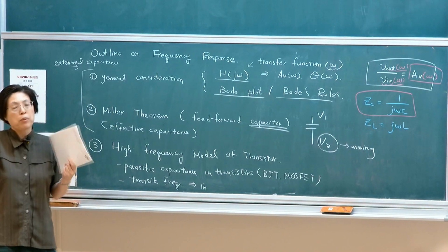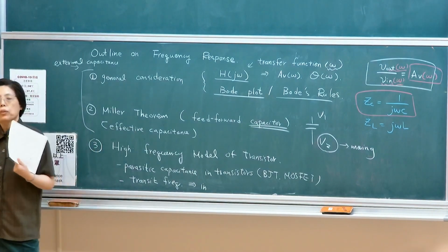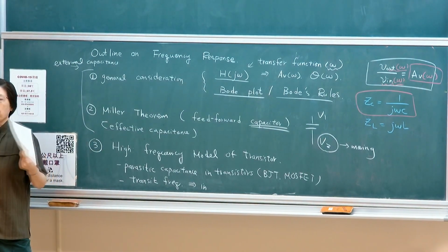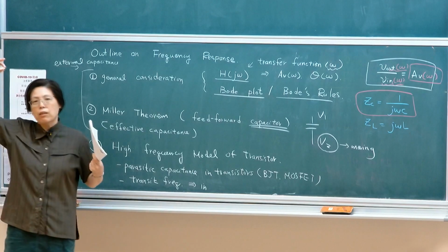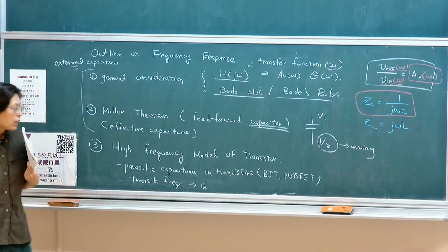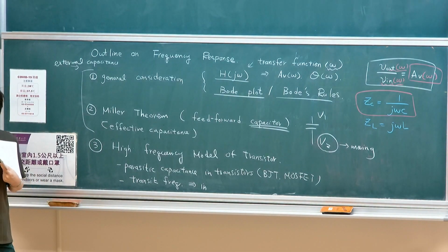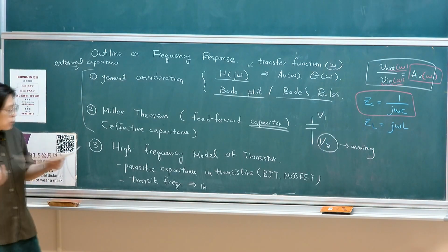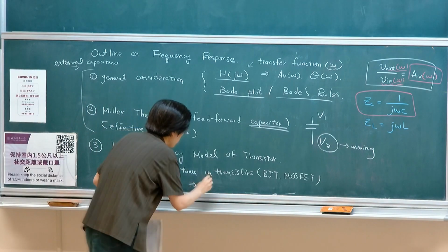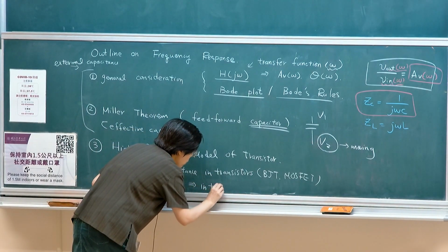If you have the most ideal case, for example, a common source amplifier with an ideal current source load, that will give you the maximum gain, the ceiling of your gain. That's called the intrinsic gain. In the frequency domain, there's also a boundary, which is the ultimate speed of your transistor. This indicates what we call the intrinsic bandwidth.